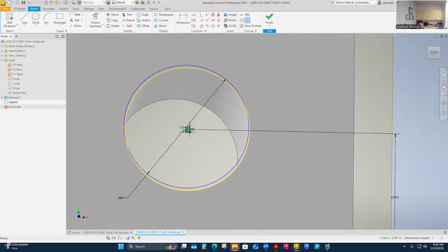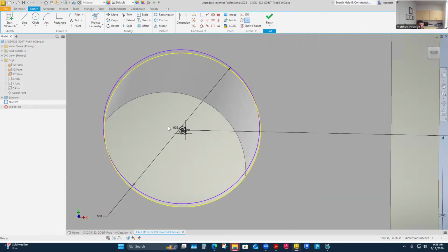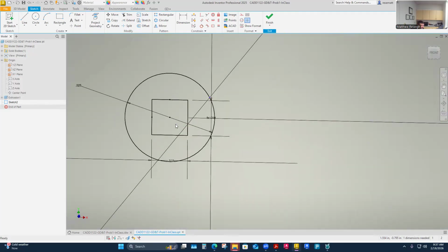And so this is what that geometric symbol means to me: as long as the center of my circle lies inside that little 0.025 diameter tolerance zone that's round in shape, that is how much my hole location can vary. You can see it arc around here. This has even increased how sloppy I can be with the position. The initial drill point of this hole can vary a lot. It's nice to know where even a baseline to start tolerancing would be.